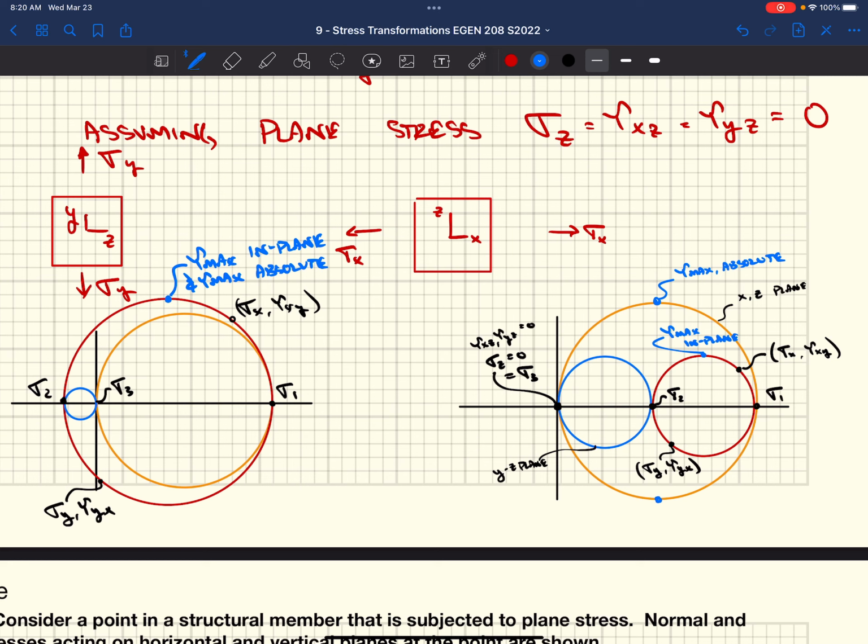Well, problems can arise when we don't capture the maximum absolute shear stress, and there's an orientation in this material in 3 dimensions. You take this block, and now instead of just rotating it this way, in the XY plane, we're starting to rotate it in 3 dimensions. So there's an orientation in there where we have a greater shear stress. And that can be bad. We might say it's okay because all we do is grab this. Well, in reality, somewhere in that material, at some orientation, there's a stress that's greater than that. And that could be greater than the stress the material can handle. Maximum in-plane versus absolute.